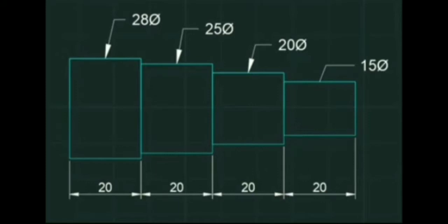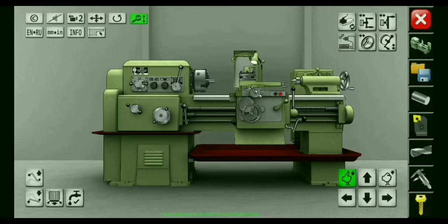So this image is the given plan, or what the mild steel's result should be after doing facing and turning operation. Before I proceed to the facing and turning operation, the cutting speed of the mild steel I'm going to use is 90 meters per minute.